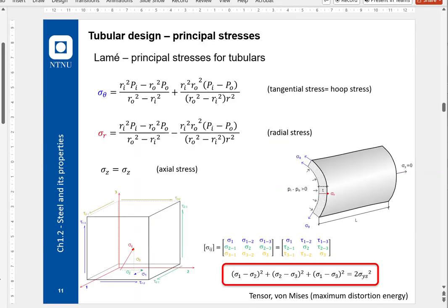All right, and here with the, sorry about the disturbance. Here are the expressions for the principal stresses for pipe. We can thank Mr. Lamé for these principal stresses, and that simplifies everything so much. We can now design or find the limit. We can find the limit. We input whatever is the acting forces in any situation, and we see it up to the limit of the yield.